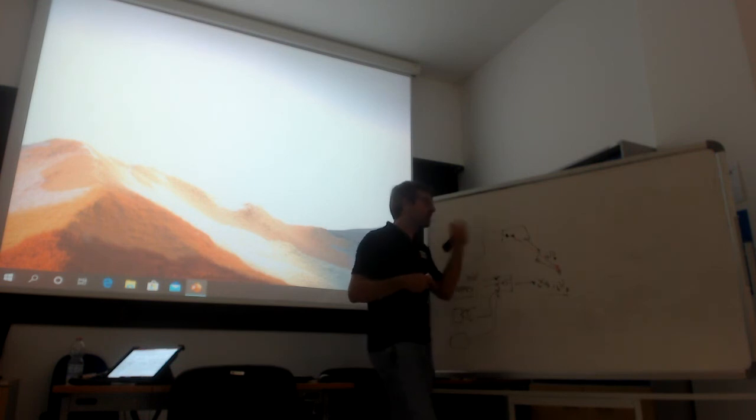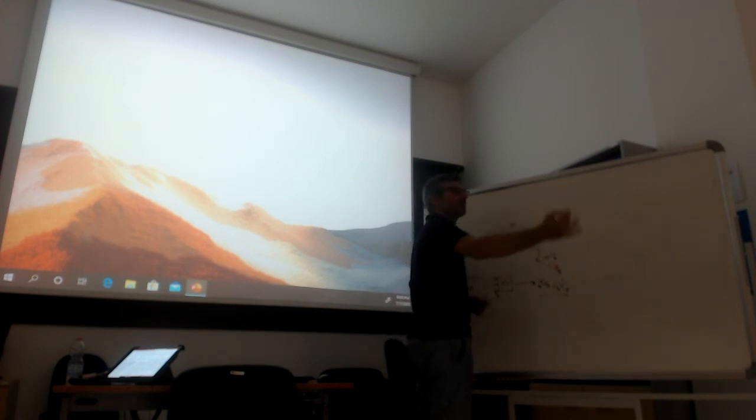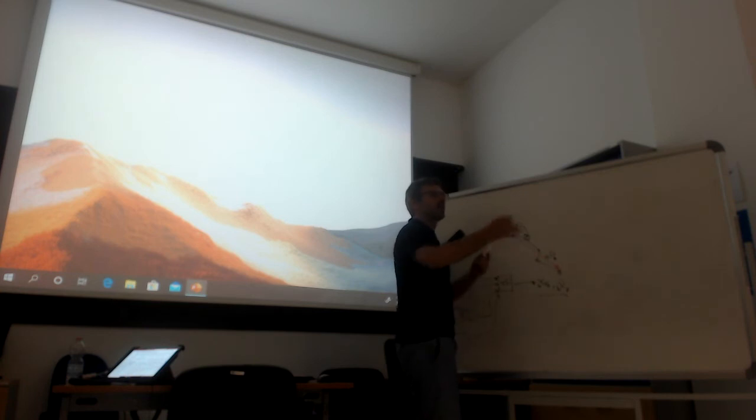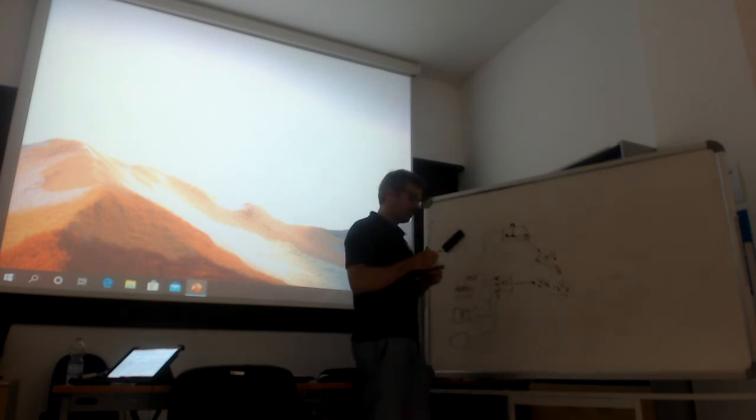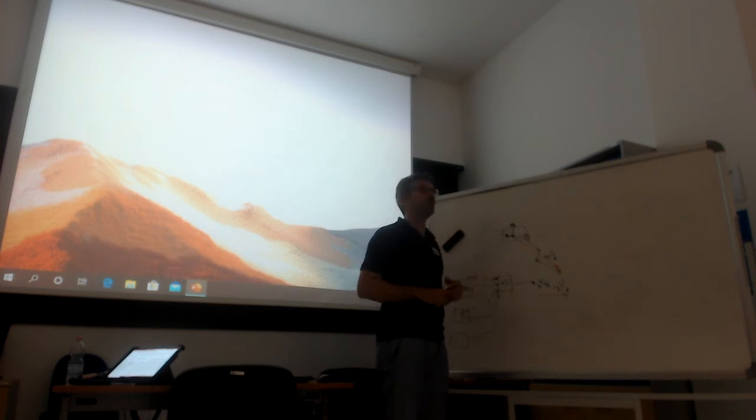In that case, you continuously move the base. You can reset, do dead reckoning. You reset the base at the beginning, and this is the trick in essence, to avoid the accumulation of error, or the drift, in the state estimation.